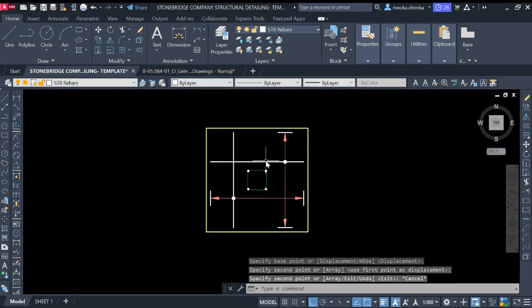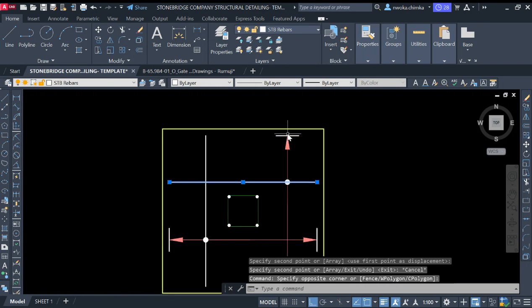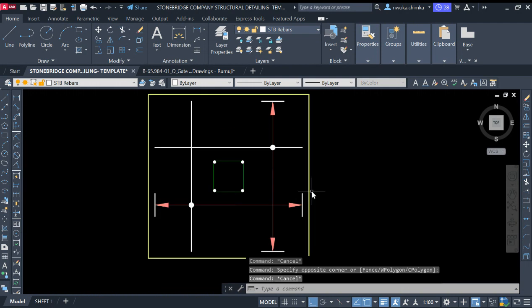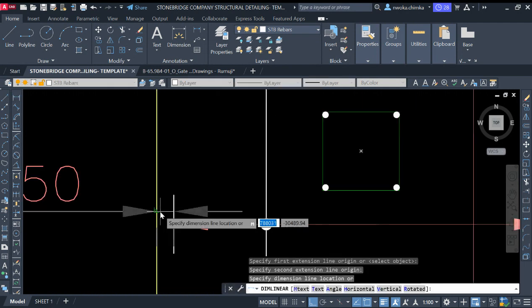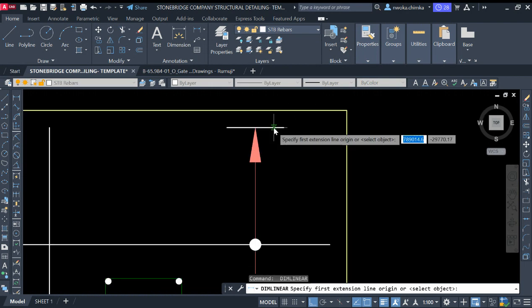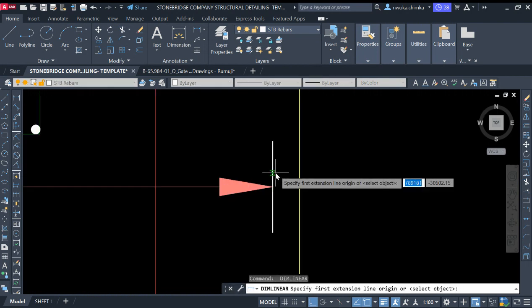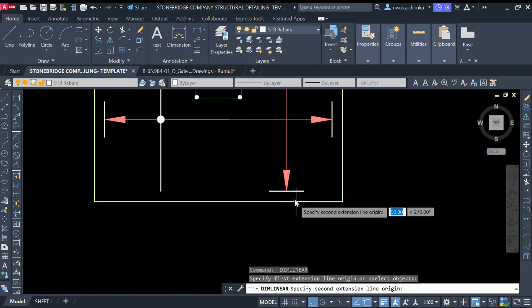So right now we have now shown how this bottom bar for this footing is running. It's running from this point to this point, and also from this point to this point right now. Okay, so right now, if you check also our cover, it is still 50 millimeter. You can see it there. Also at this point, the same thing happens here. So we are still okay. And also at this point again, same thing happens here. We are still okay. And then also here again, we are still okay with that.